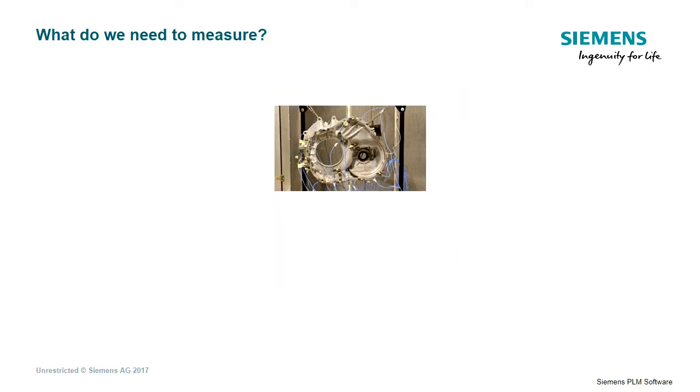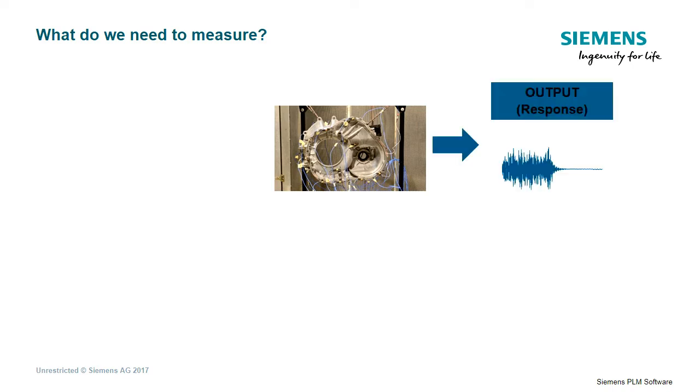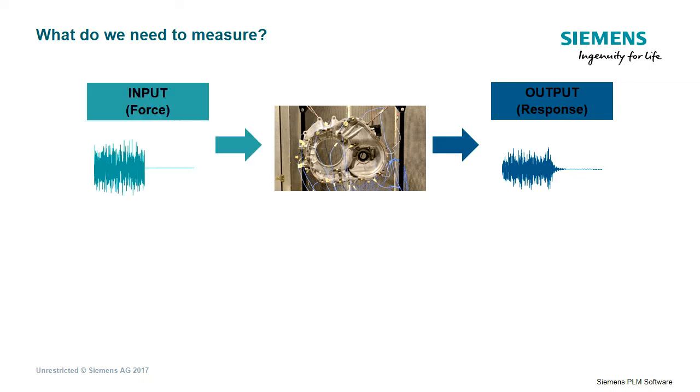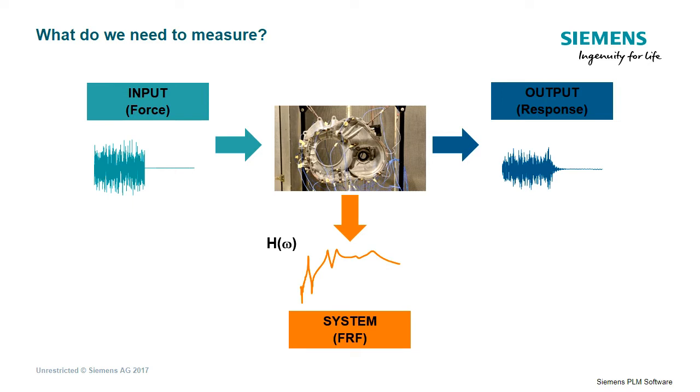To perform experimental modal analysis, we need to record the responses at several points of a structure due to a known applied excitation at one or more locations. From this measurement, we can then identify the system frequency response functions.